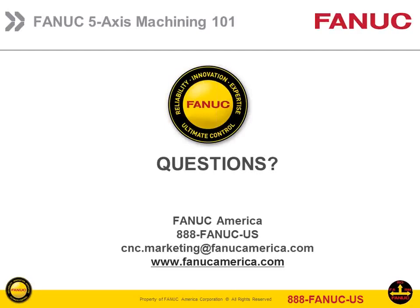as Rick has really beat into my head, and then I tried to reiterate it in our presentation today, one of the first things you need to do in the program, you've got to identify the part location. You've got to tell it where it is. So that's why it's critical to use the workpiece setting error compensation along with the tilted working plane. You've got to tell the machine where the part is. It's important that you do that.